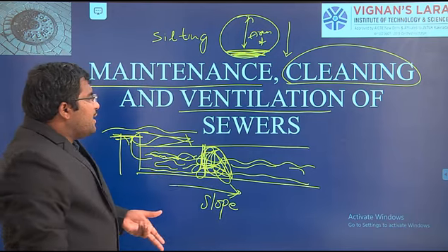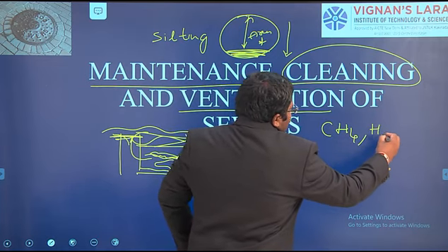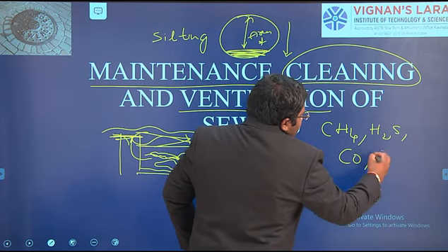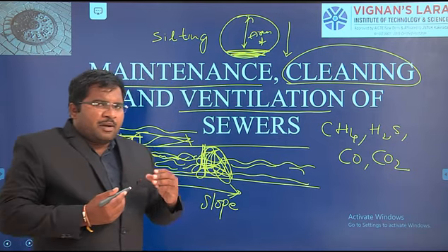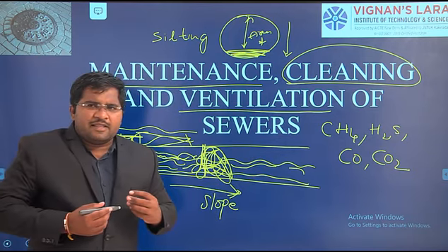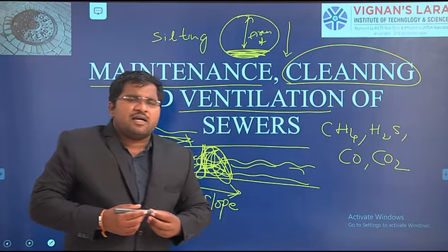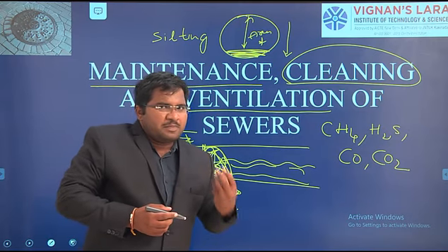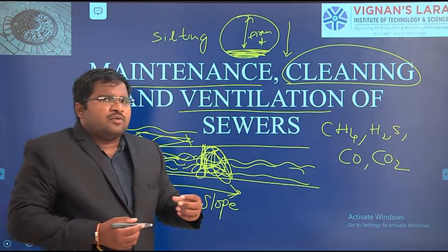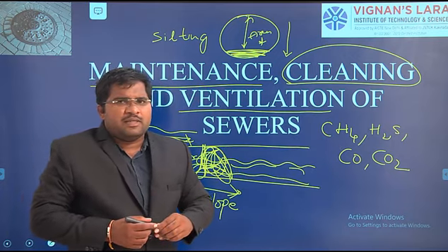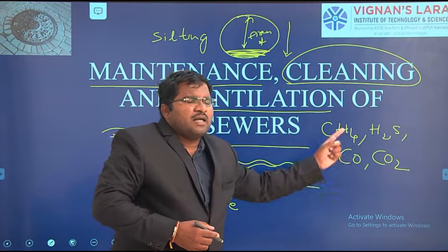During that, methane gas, hydrogen sulfide, carbon monoxide and carbon dioxide will be evolved. Among these, methane is flammable and most hazardous. H2S causes too much smell, and due to that odor, workers who enter the sewer pipelines for cleaning may die. Those kinds of situations will arise.